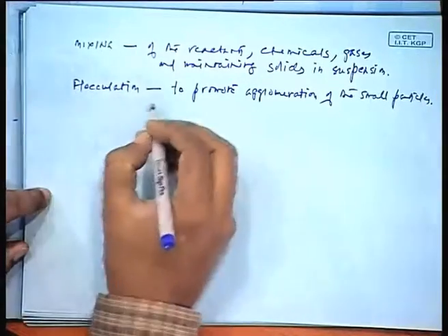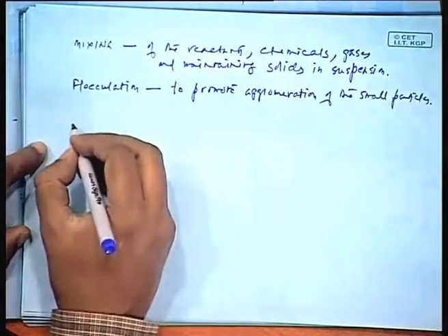So one aspect of alum use is agglomerating small particles together. As a result, the mass actually increases. Once it gets agglomerated, the density increases, so it begins to settle or remains suspended at one point, and they also become visible. Even as small particles in solution they may not be visible, but when they agglomerate, it becomes more visible. You come to know what parts are to be removed. So this is agglomeration, or flocculation. Flocculation is a very important part of wastewater engineering.